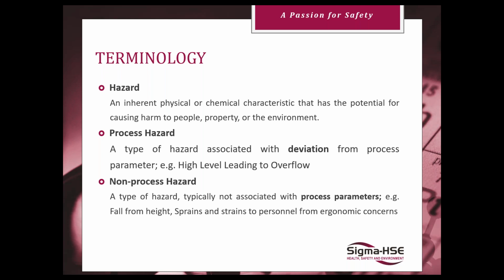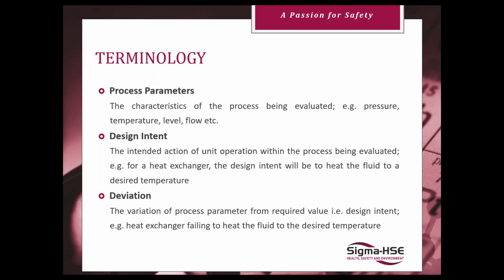And then there's non-process hazards, which we're not as concerned about in the PHA. These are generally handled through your job site analysis and your field safety. Do you have fall from height concerns? Are there potentials for slips, trips, and falls? Improper PPE being used for the tools. That falls outside the realm of the PHA and the HAZOP methodology, but you still want to make sure you're capturing them using the correct tools and methods.